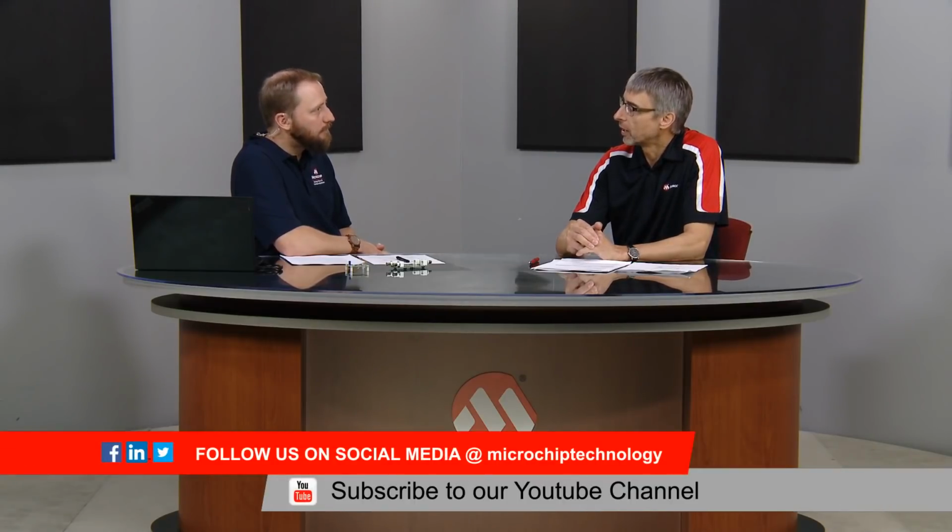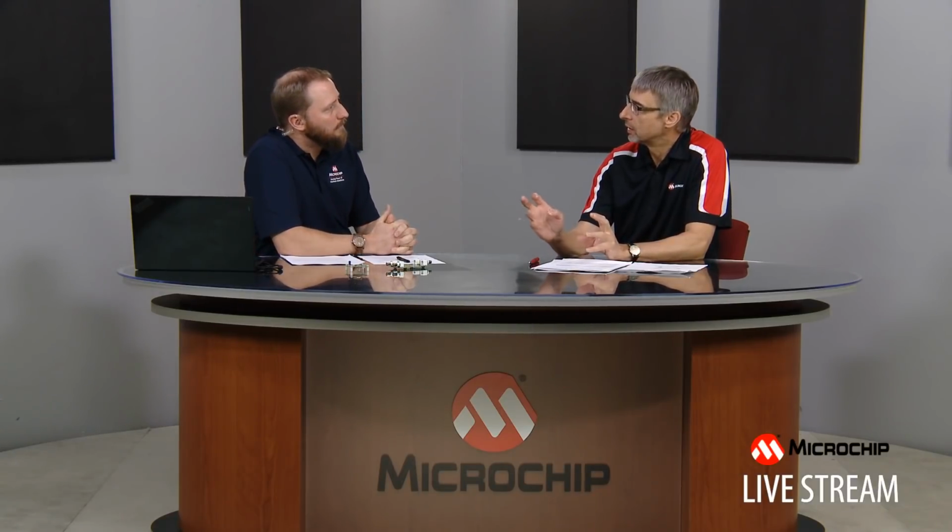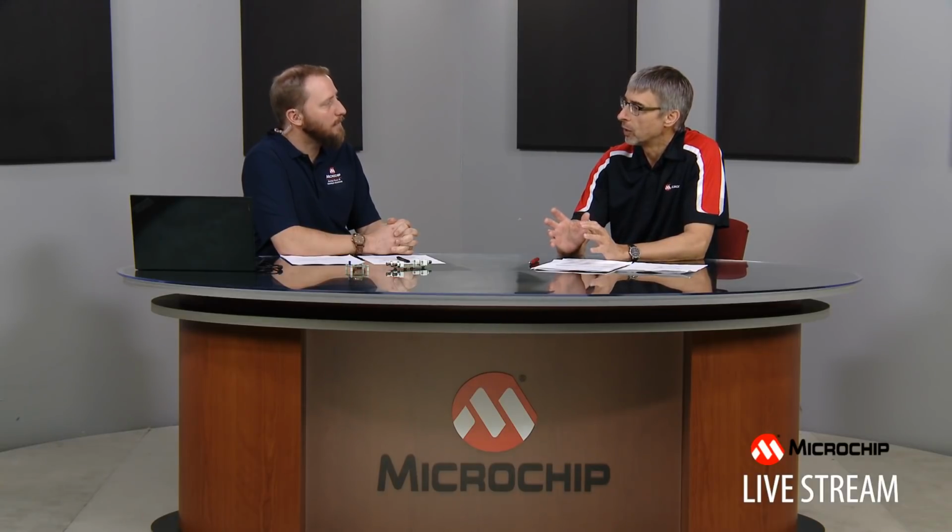So, Stefan, you touched on this before. Yes, that's actually a very good question, because I mentioned auto zero, for example. That is an architecture that was used initially, and the main difference here is auto zero uses a sampled system where actually the input is sampled, and then the inputs for the correction pass are switched off of the inputs. Now, typically you will find, if you compare specifications, that the auto zero leads to an even lower initial offset, and maybe it's fair to say also a little bit higher on the drift.